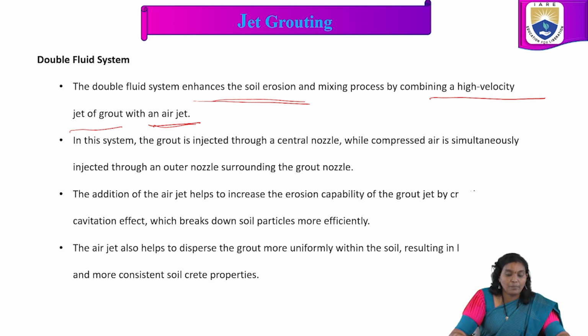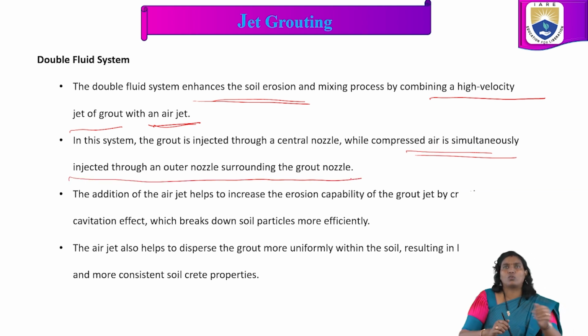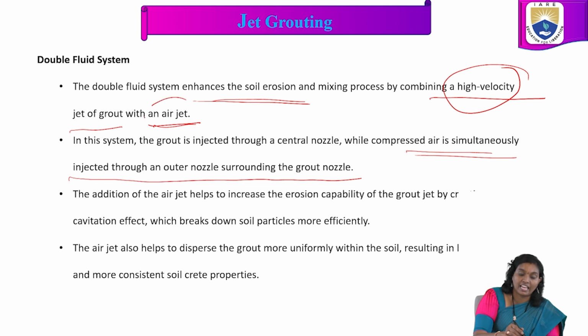So in this system, compressed air is injected through an outer nozzle surrounding the grout nozzle. We are combining the high velocity grout jet with an air jet.